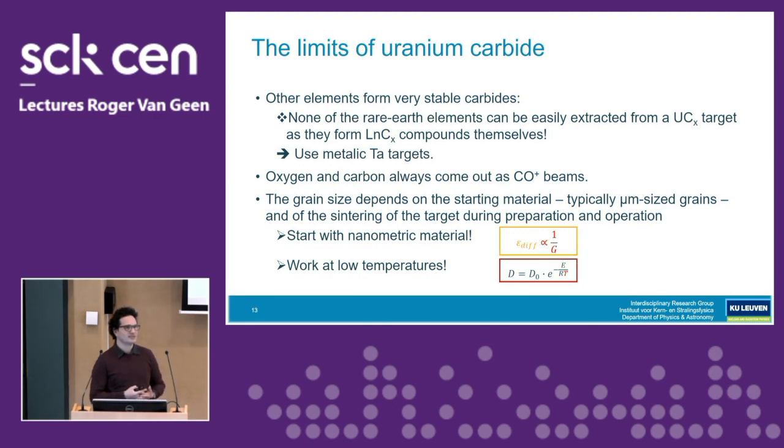Well, yes, but what about the diffusion? So you see here, it's the opposite problem. With the metal, you would want to push the temperature higher. You're limited there because it's going to melt. If you go to ceramics, you say, oh, let's now push it to higher temperature. But there, what you get is densification, pore closure. You also kill your diffusion. It's not the integrity of your material, but it's the release that you are going to kill in that process.